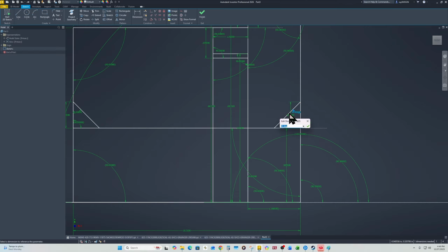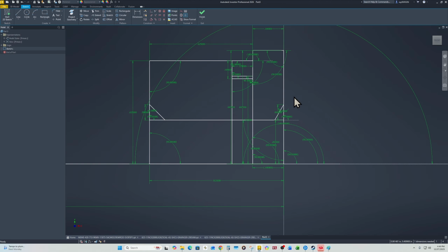Actually, might as well just do 30 degrees on one side, 40 degrees on the other, 45 degrees, I mean, regular 45 on the other. And extract, we're getting 30 on the first one. And we'll just see the difference on how it looks once it's modeled, because we're basically simulating the tool. When we coil it, we're basically simulating the tool going. We're basically making a small program cutting the tool.